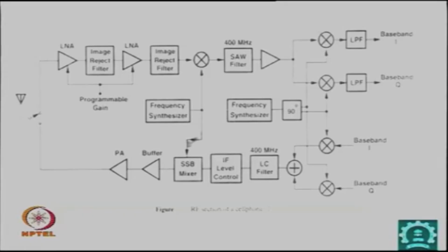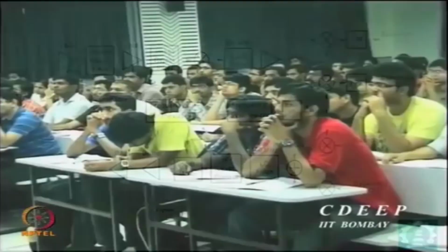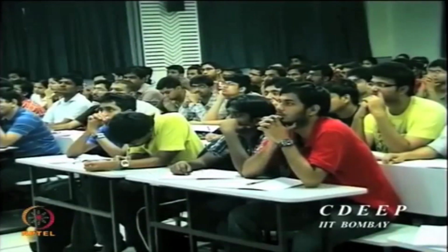So if you look at the typical RF part in the mobile, this is what it typically is. Once you are in baseband, all digital signal processing will start, and you will have A to D converters and then everything digital. So the reason we wanted to put all this IF down is that otherwise the requirement for conversion using the ADC will be huge capacitors.